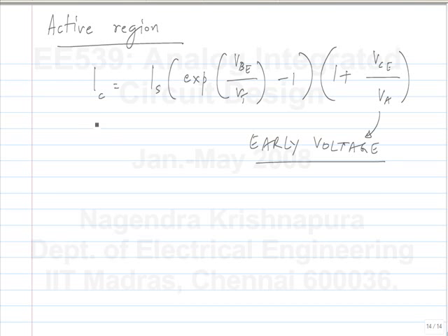And also the other important difference is that there is a base current which is related to the collector current by a constant beta, which is preferably very large, okay. But typical values may be in the tens or hundreds at most. So what do we do? How do we generate the model? So we have these two currents. We differentiate it with respect to all of the voltages and get the conductances to get the small signal model, okay.